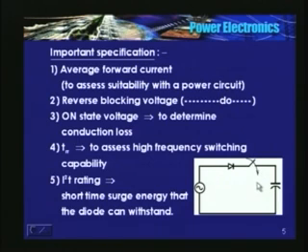Assume that I am closing the switch at omega t is equal to pi by 2, or at the positive peak. Capacitor is totally discharged. So in other words, there is a short circuit here. Capacitor voltage cannot change instantaneously. The instantaneous value of voltage at this point is at the peak and you have closed the switch at that time.